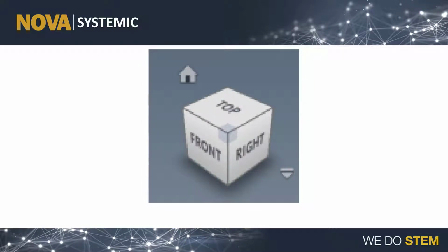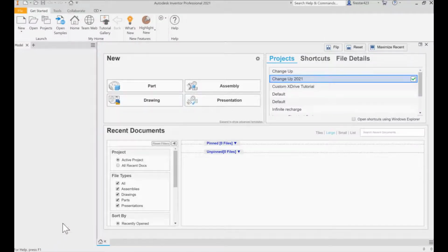One final thing is the orientation cube. This cube allows us to rotate our view around the part. When we hover our mouse near it, it becomes clickable and we are able to click and drag to rotate our part around. Also, in the top left of it, there's a little house, which if we press it, it'll go into the resting view, where we can see all 3 sides of the part. You will see me use this tool later, although I did not point it out at the time, so, in compensation, I'll call it out on screen. And now, let's get started.